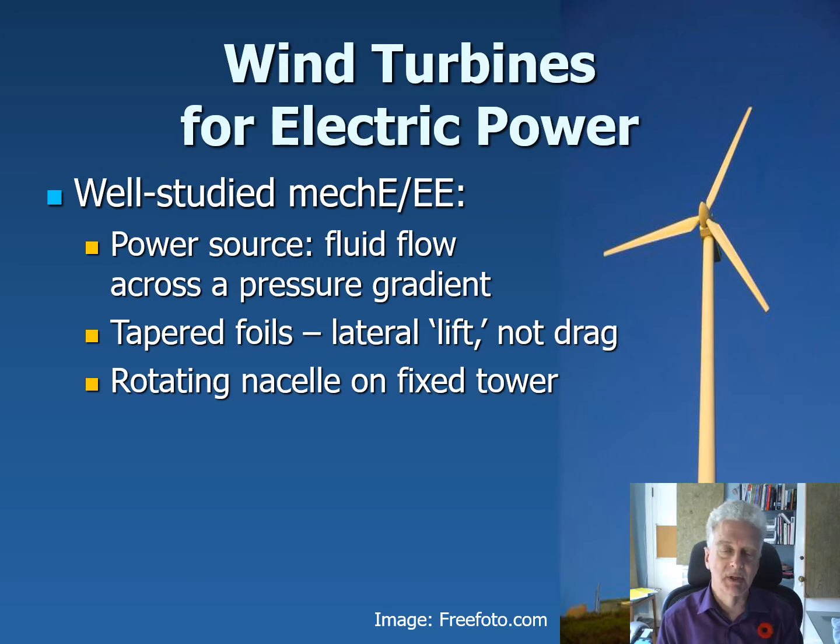They have to be shaped like the blades of a propeller or an airplane wing, and they use the Bernoulli principle to cause lift, and that lift goes around the circle of the blade's rotation. Then they're connected through a hub onto the power shaft, which is in a nacelle. That's just a covering that keeps the turbine generator out of the rain. And then that is on an axis that can rotate around to face into the wind on top of this fixed tower that you can see at the bottom.